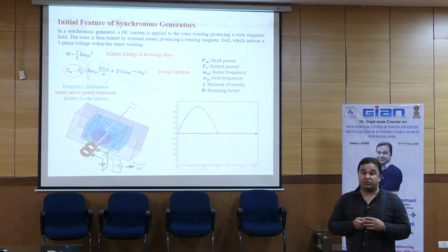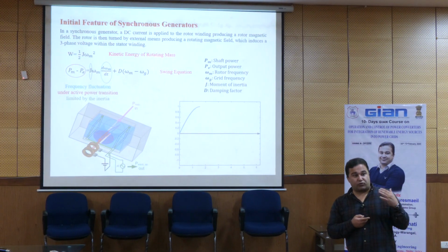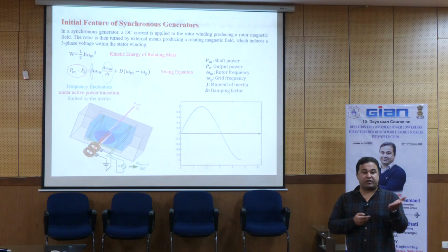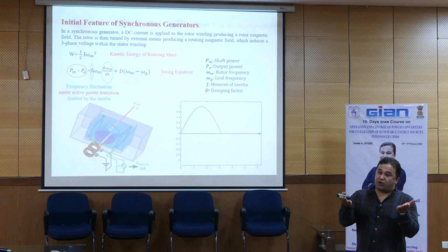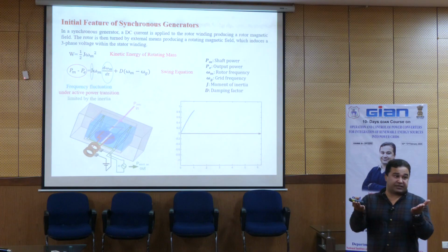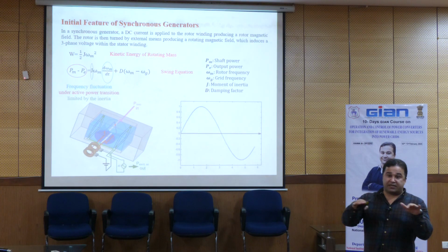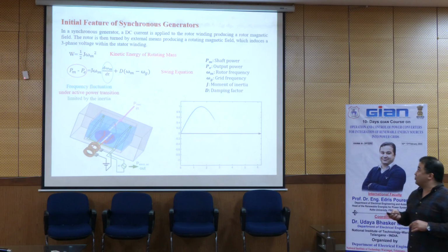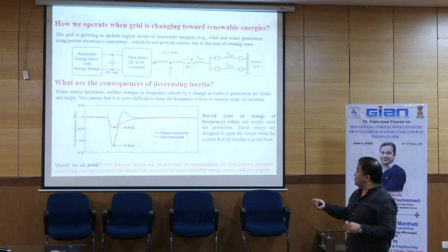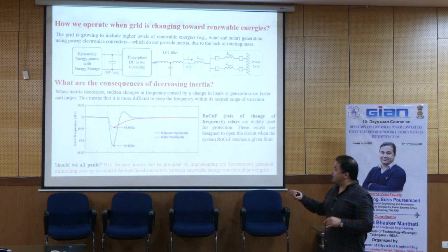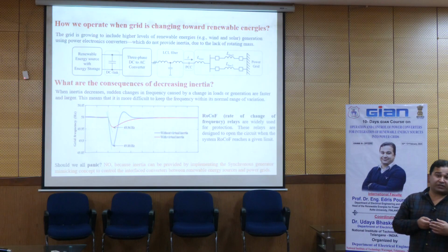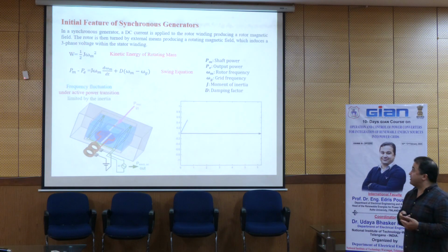By using this technology, we can provide the required inertia for our system, and when we increase the share of renewable energy sources, in parallel the kinetic energy also increases, and then the grid will be strong enough to survive. So if you look at this one, it works like this one, not like this one. So you have a virtual inertia, or provide inertia in the control loop of the converter-based generator.